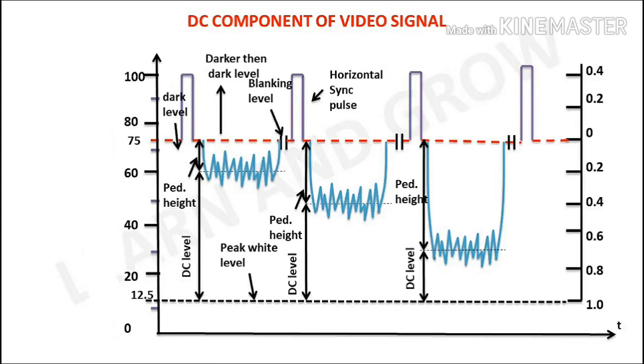During the entire vertical blanking period, no image information is generated, because the signal level is black or blacker than black, so that the repetition of the vertical trace can be blanked. The details of all these pulses in the vertical blanking interval are summarized in Table 7.2.